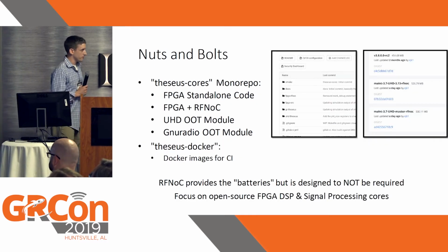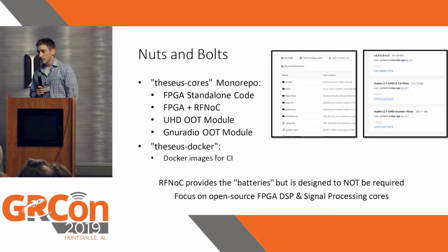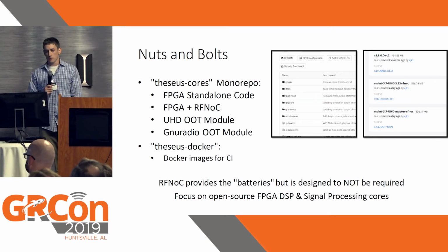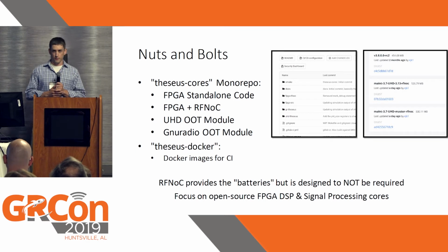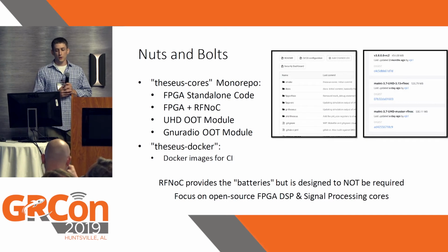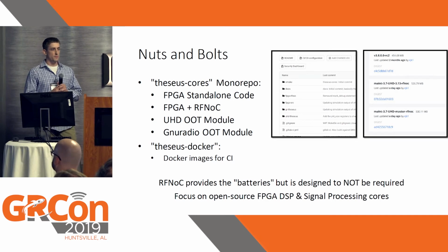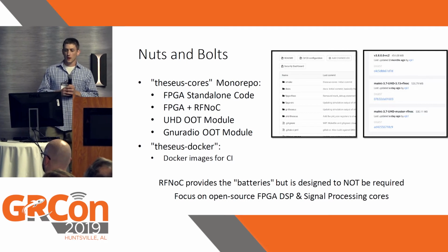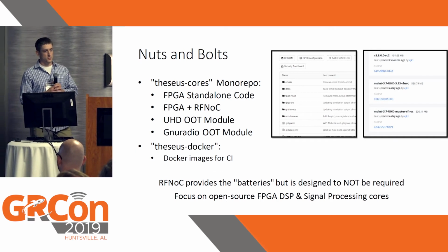Quickly go over some nuts and bolts. So the way I've set this up is, and I'll also talk about what it provides right now, I've set this up as what you might call a mono repo, I suppose. So the core of it should be FPGA standalone code. So it's not tied to any infrastructure, but it does something like provide a polyphase channelizer. Then there's FPGA wrapped by RFNoC. We could also iterate on this and add other things like FPGA libIO or FPGA MathWorks, whatever your tool of choice would be. We provide a UHD-based out-of-tree module to interact with RFNoC and provide the software hooks.